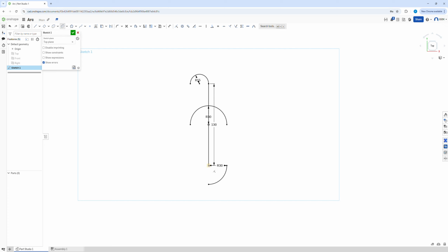The next option we've got is the elliptical arc. Exactly the same thing. I'm going to take this point, I'm going to drag out for my ellipse. Let's go horizontal here, and then I can basically start, depending on how wide I want it to be, my next part of the arc. So if I was to say I want it to be roughly this wide, I can drag around, and then we have got our arc. So let's make that vertical there.